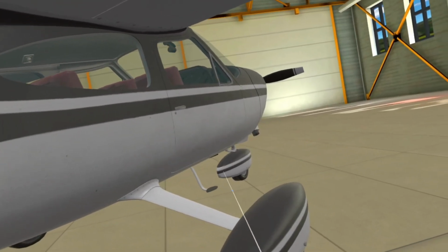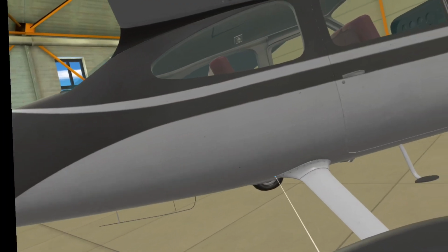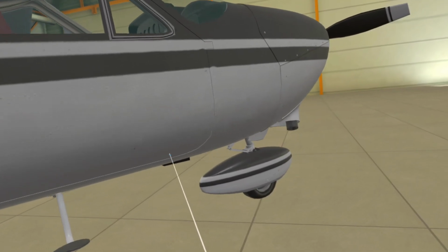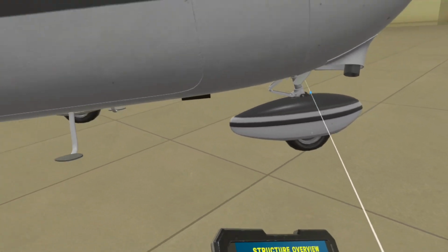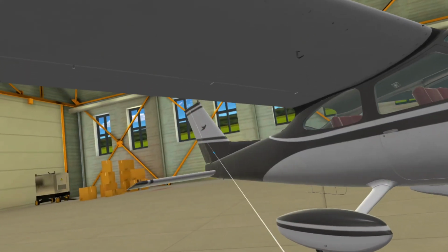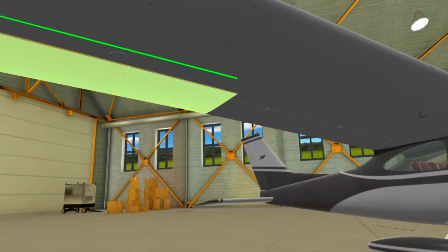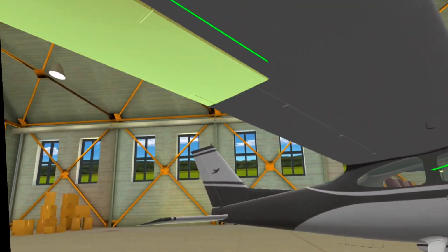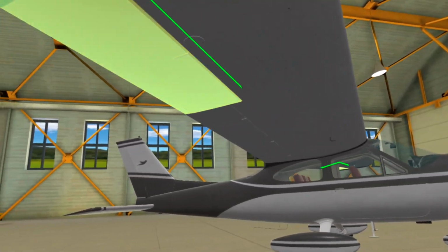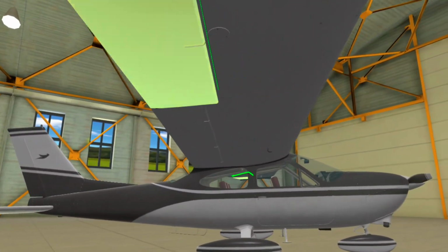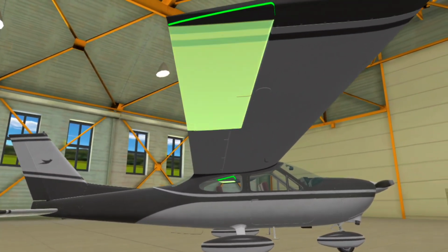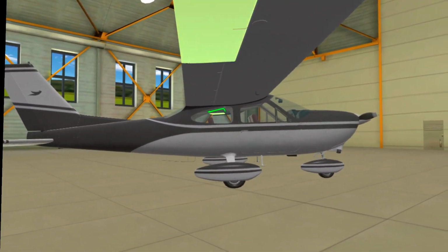The primary control surfaces that you will find in all airplanes are the ailerons, the elevator, and the rudder. The ailerons are on the wings. They control the roll of the airplane. The ailerons are controlled by wires connected to the main control hub, where the yokes are also connected, which, similar to a steering wheel of a car, will move the ailerons and in turn the airplane to the desired direction.